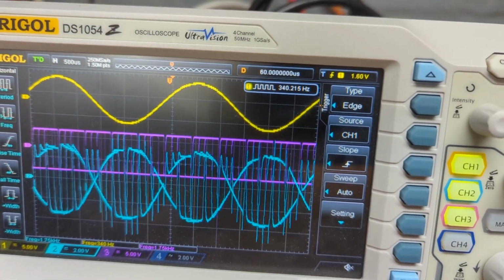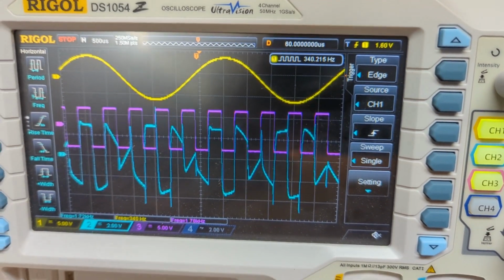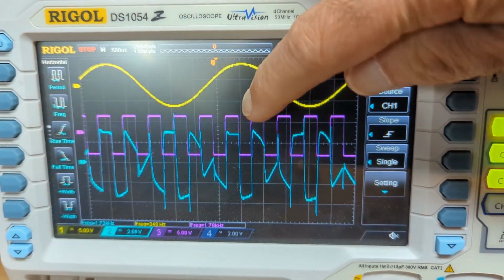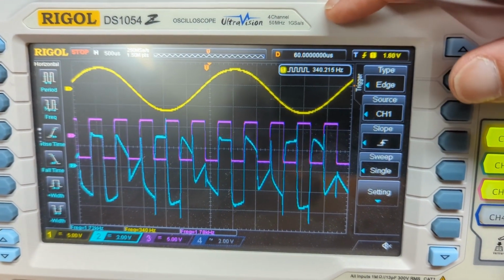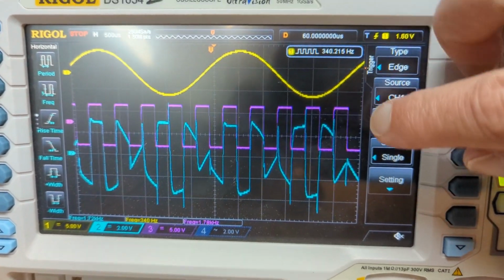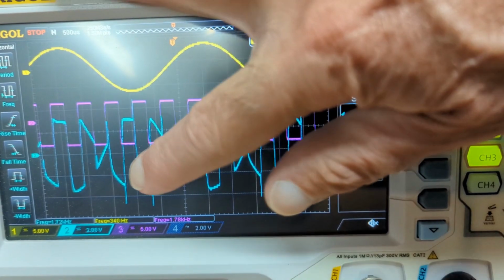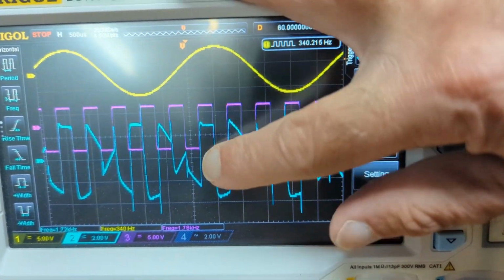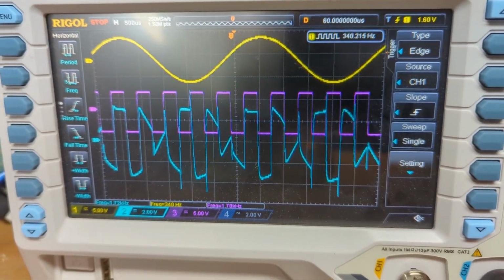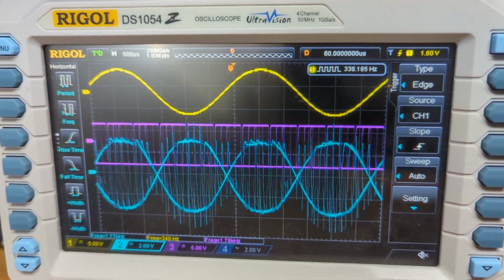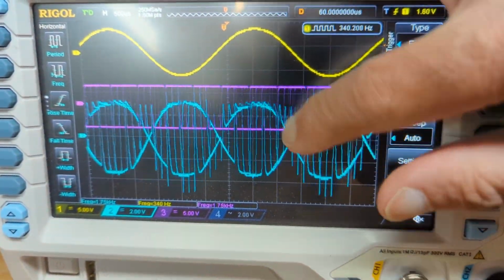If I just give you a single trace here, this is just what happens at one moment, and there now you can see this carrier is this square wave, and the output of the ring modulator is this thing here, which if you squint at it, it's like a sine wave, but it's chopped up and going back and forth and back and forth and back and forth. And then if you look at multiple triggers, then you can see it's got this sine wave overall shape to it.